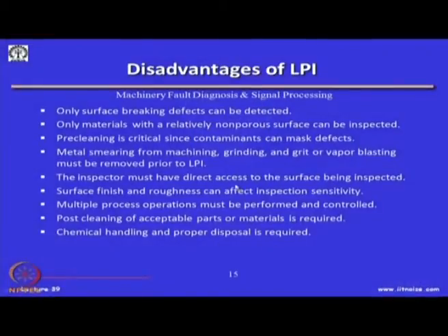Okay. So, some of the disadvantages of LPI: only surface-breaking defects can be detected, and only materials with a relatively non-porous surface can be inspected. Pre-cleaning is critical since contaminants can mask defects. Metal smearing from machining, grinding, and grit or vapor blasting must be removed prior to LPI.